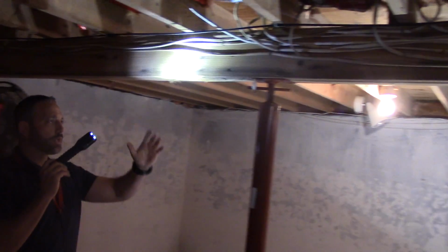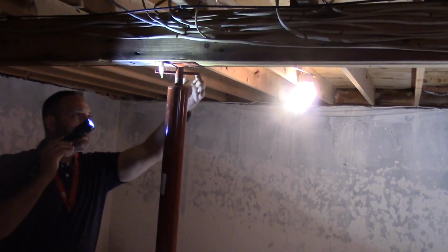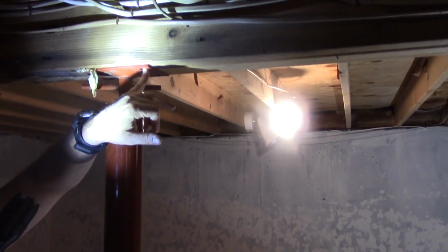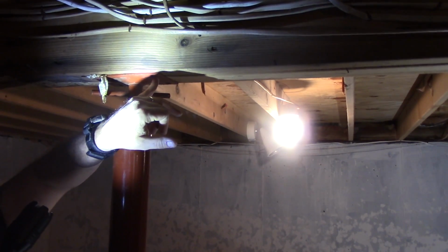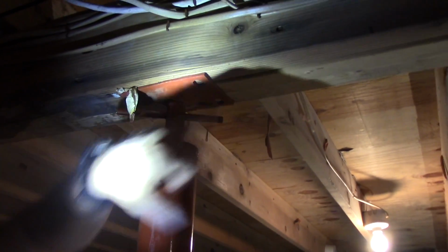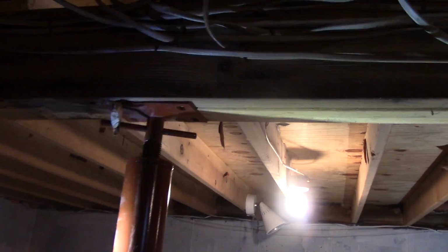As we move forward, we can see that we have a supporting beam. Here, we do have a defect because there are no fasteners attached to the plate, and typically there's a nail which would then be crossed over here, so there is no movement. Next, we're going to be looking at the overall condition. We're going to be coming down here, looking at the plate. Again, there should be some sort of fastener that's attaching this, just in case so we don't have any movement.